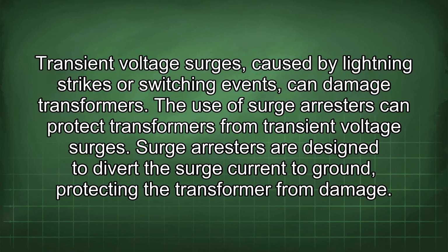Transient voltage surges caused by lightning strikes or switching events can damage transformers. The use of surge arresters can protect transformers from transient voltage surges. Surge arresters are designed to divert the surge current to ground, protecting the transformer from damage.